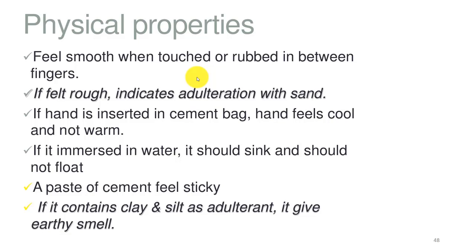Because the hydration reaction is an exothermic reaction, it involves a large amount of energy, heat. So it's a highly exothermic reaction. If the cement is hot, you can say that the hydration reaction has already started. So you cannot accept cement which is hot. Secondly, you can just touch the cement and make sure that it's very smooth. Otherwise, it might have an adulteration of some stones, dust, and some sand. Make sure the cement is very smooth by touching.